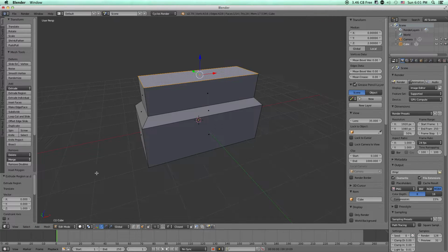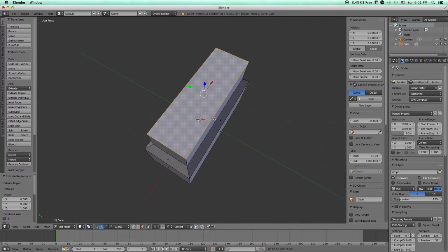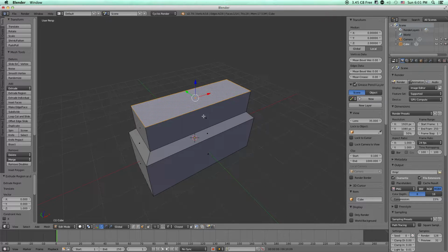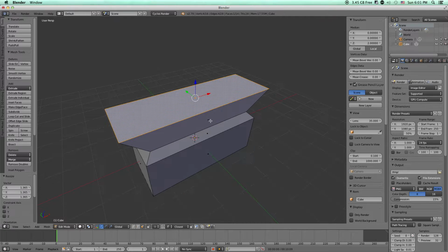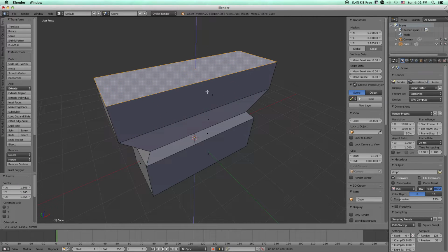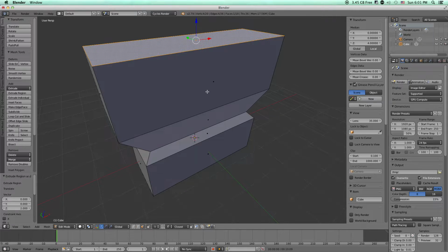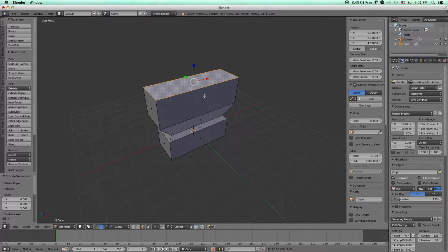Over in the bottom left corner, it will show you what dimension you typed in. And then you can say scale, go up, extrude, go up, let's type in 2, and then extrude. And if you just click without moving the mouse, it will stay right there.